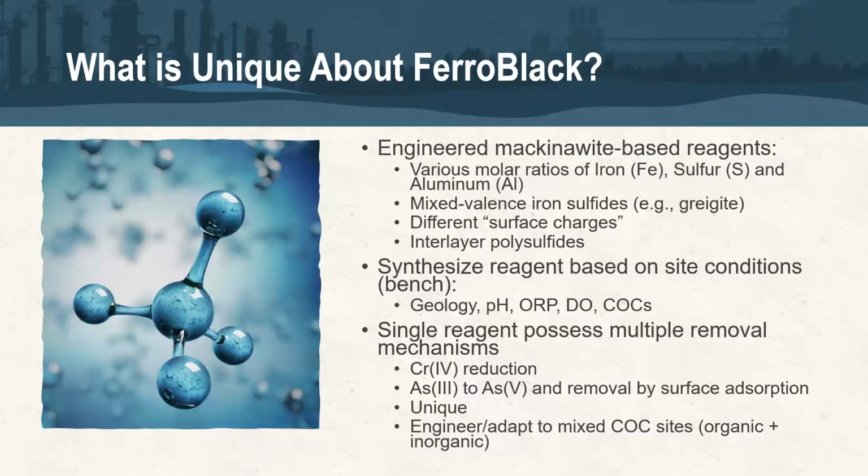And I know if you've worked with us at AST before, we do a lot of stoichiometric calculations and assessments based upon groundwater and soil data. We don't necessarily do a bench test. However, in the heavy metals realm here, I would absolutely recommend doing a bench test, because it becomes very site-specific with these types of reactions that cause reduction, co-precipitation, right, convergency. Something like arsenic, right, different pHs, different ORPs is going to react very differently in situ than, say, something like a benzene or PCE would with some very minor swings in pH or even ORP or DO.